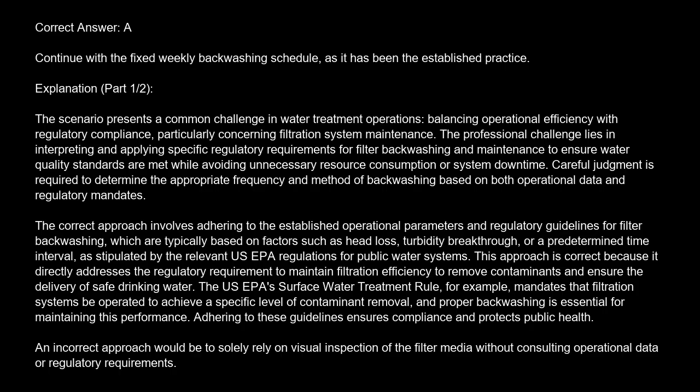This approach is correct because it directly addresses the regulatory requirement to maintain filtration efficiency, to remove contaminants, and ensure the delivery of safe drinking water. The U.S. EPA's surface water treatment rule, for example, mandates that filtration systems be operated to achieve a specific level of contaminant removal, and proper backwashing is essential for maintaining this performance.